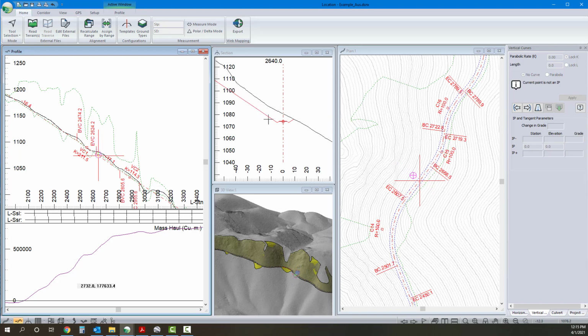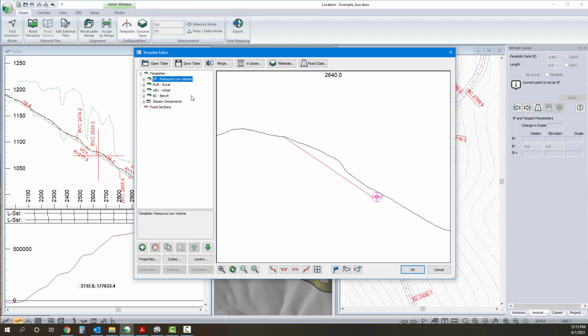So we have our cut slope here that follows the ground to the top of the hill. This really isn't practical to build, so in this case we're going to oversteep. Now if we oversteep in this, we expose ourselves to surface flow coming from that steep face, eroding it and destabilizing it. But we can try to manage that problem by benching it and directing the water along those benches.